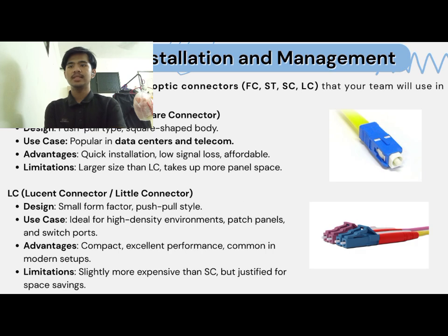The third type is SC connector, or also known as subscriber connector or square connector. Its design is push-pull type, and it also has a square shaped body. Its use case is popular in data centers and telecom. Its advantages are quick installation, low signal loss, and affordable. And its limitations are larger size than LC connector, and it takes up more panel space.